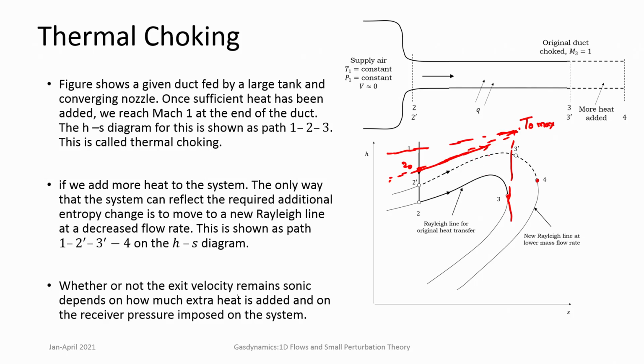So, we have discussed mass flow rate choking in the context of variable area ducts, and friction choking, which relates to the length of the pipe, in frictional flows or Fanno flows. Now, in the case of thermal or Rayleigh flows, you have thermal choking, where flow achieves Mach number 1 due to heat being added, and that is the maximum amount of heat that can be added. Suppose you want to add more in the case of a subsonic flow, then exactly similar to what happens in a Fanno flow condition, you can have two cases.